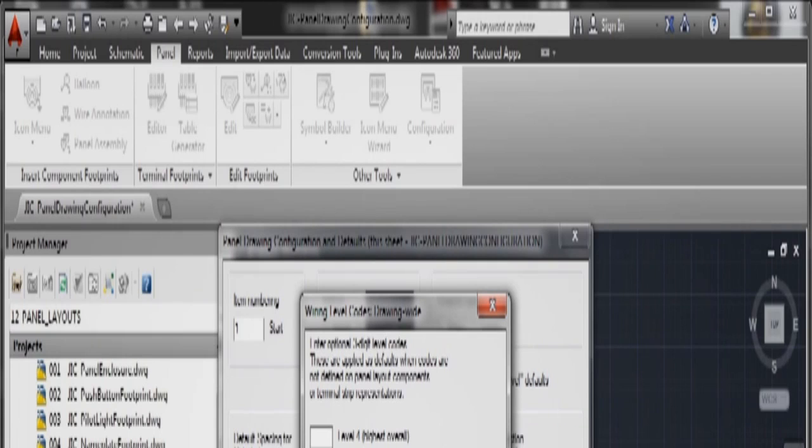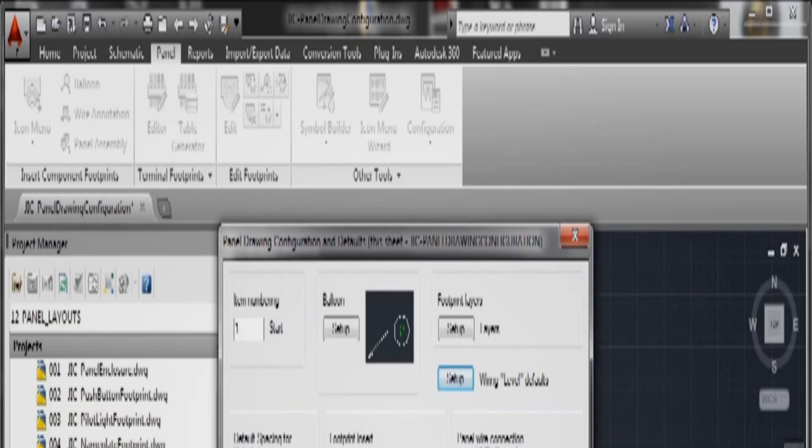So you've got lowest, subplate or pan, and then the next level up might be another level above that wiring, and so on and so forth. So just be aware of that with AutoCAD Electrical. You can have your wiring on different levels. Panel wire connection, XYZ offset reference. So you can set, if you've got levels, you're going into almost 3D territory. You've got XYZ offsets and things like that.